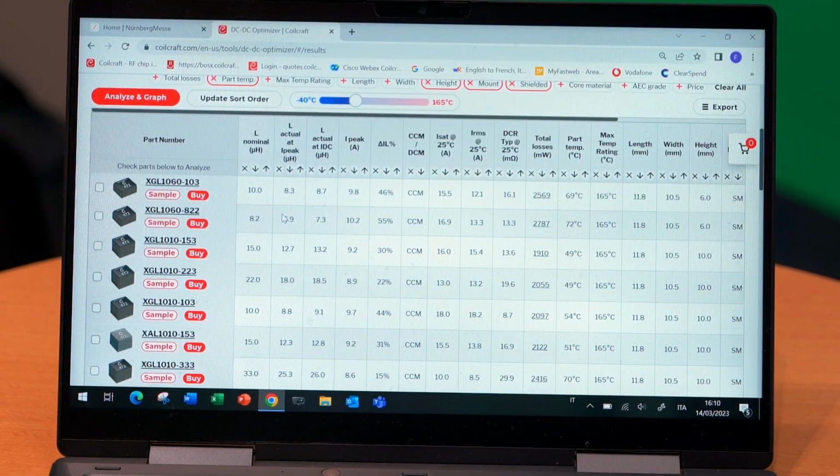Yeah, exactly. Everything is interacting, all the parameters. So relaxing one parameter can have a beneficial effect on others. In this case, allowing a higher ripple, we could go down with the height and eventually take the 6 mm part into the game. And now we can just focus on what we got here. Because before that's gone from 10 millimeters to 6 millimeters, hasn't it? Yes, it's a substantial reduction in height. Exactly. 4 mm less in height can be quite relevant.